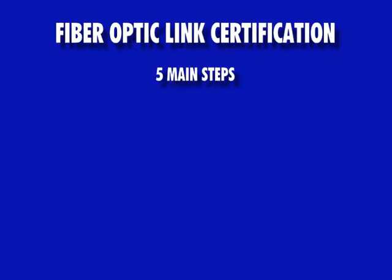I'm Professor Jim Powers. This video will demonstrate how to certify a single-mode fiber optic link using a WaveTester optical power meter and a WaveSource series single-mode light source. There are 5 main steps in the process of certifying any fiber optic link.